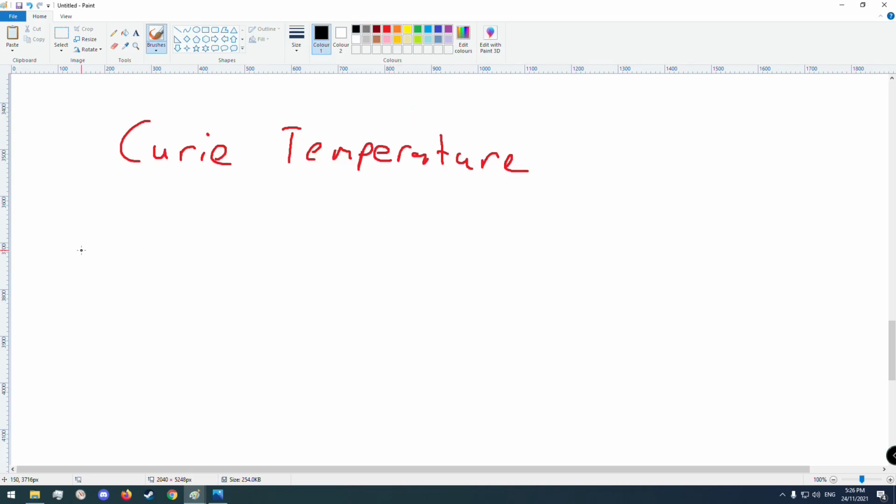For example, the lower grade a neodymium magnet it is, often the higher its Curie temperature, and vice versa. A stronger neodymium magnet can have a lower Curie temperature. Neodymium magnets can have a Curie temperature of as low as 80 degrees Celsius, which is below boiling point. I have seen videos of speakers that have been working and have got so hot you could boil water on the back of the magnets.